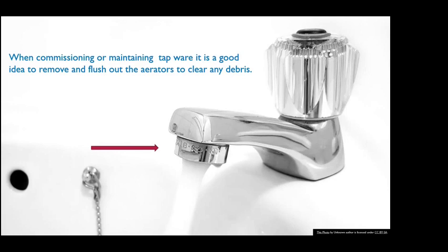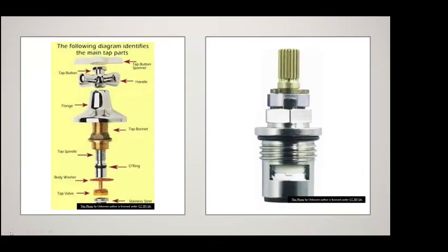Strainers are supposed to protect that, but there's not strainers on every single individual outlet. Usually there's one at the inlet to the building, and that's about it. So just try to minimize that stuff in the pipeline in the first place and flush it out.